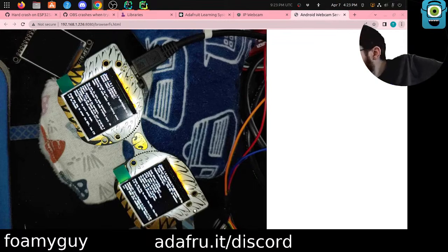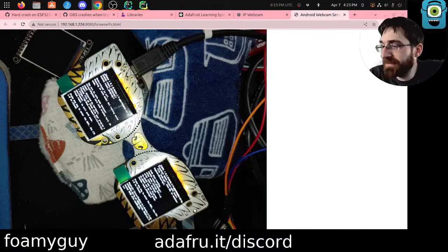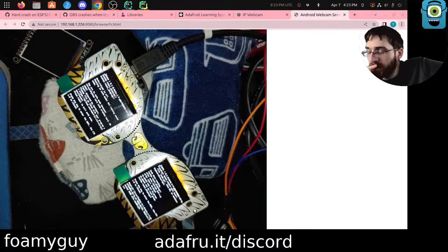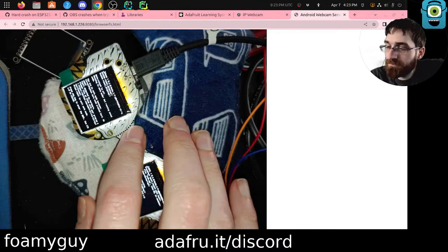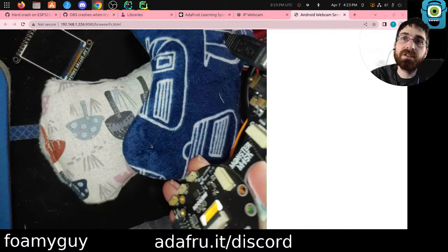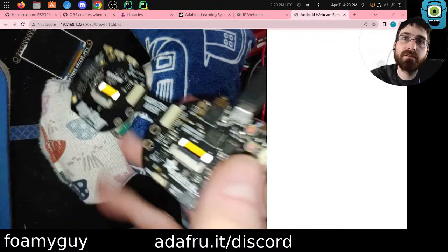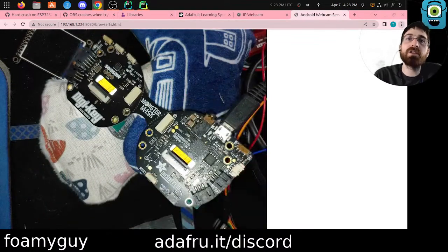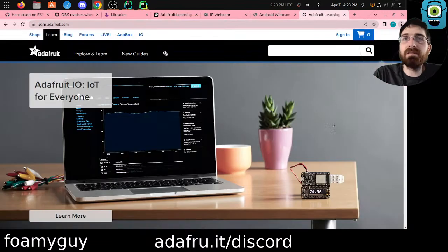So what we're going to try first is to see if I can get this to fail on a different port. This device is based on an Atmel SAMD51. Actually, let's go look at the pinouts page real fast. Let's see if there's anything. The thing is, I don't know if we can debug on this device. I want to try to get a debug build.